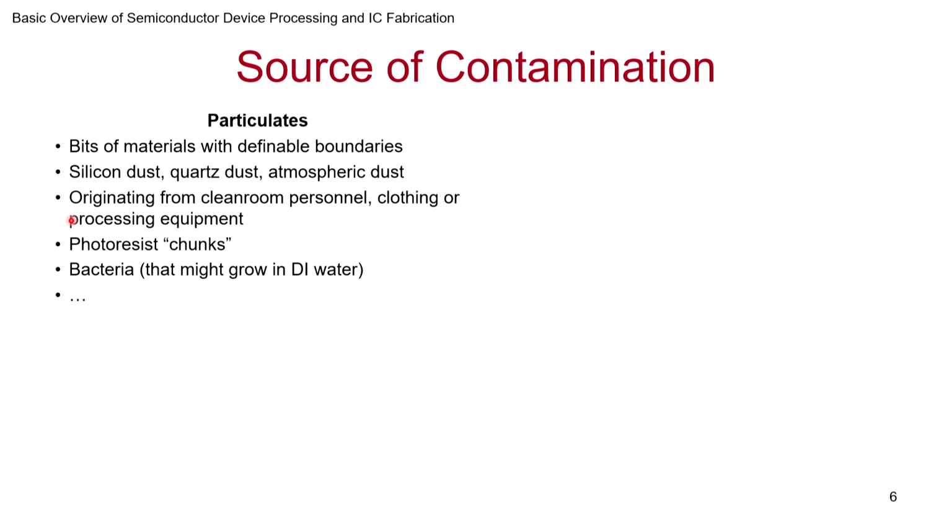Then also, it can originate from clean room personnel, people who are working there, human beings. We emanate particles. We don't realize it. When we breathe, particles come out. When you speak, particles come out. So there is protection that is given, but all the same, we need to make sure, and they do give clothing, but still you never know. Clean room clothing is worn and people have masks and so on, but all the same, there could be particulates coming from personnel. Street clothings that are inside the clean room gowns, if sometimes they get exposed, they may cause lint and other stuff.